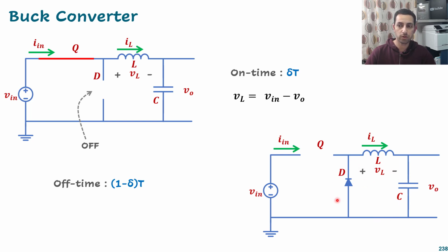Now if the inductor now has some current flowing inside it, that means that diode is on. Okay, and I think we now have a different circuit from the first circuit, and we will ask the same question: what is the voltage across that inductor? And we will answer by looking at this node, and at that node, look at this track, the voltage is 0 because now this track is 0.